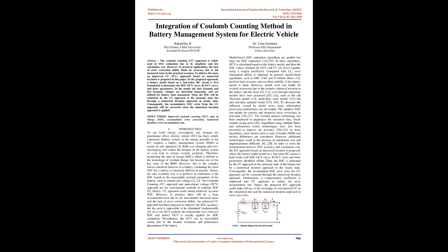Model-based SOC estimation algorithms are another hot topic for SOC estimation. In these algorithms, OCV is calculated based on the battery model, and then the SOC values obtained by OCV and CC are fused together using a weight coefficient. Compared with CC, error elimination ability is obtained.